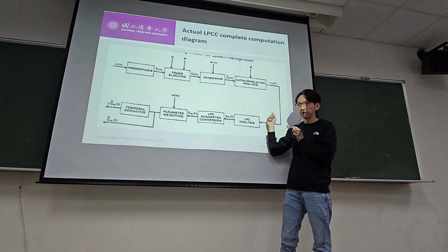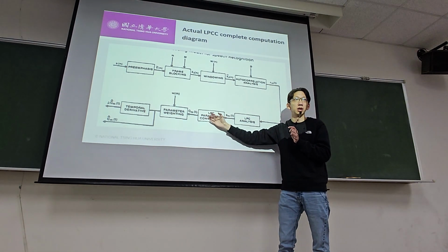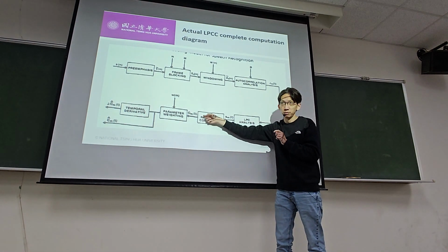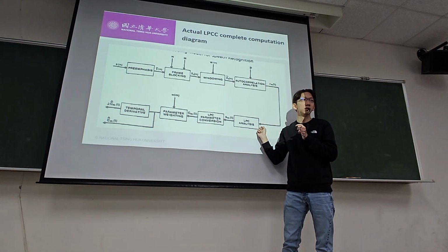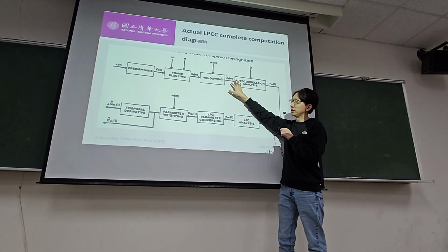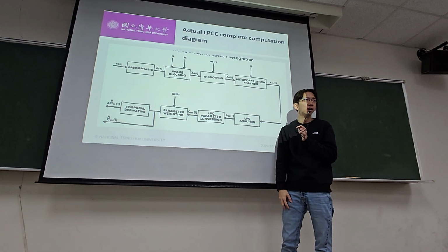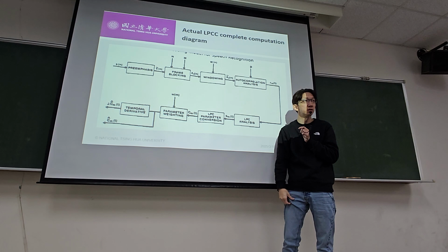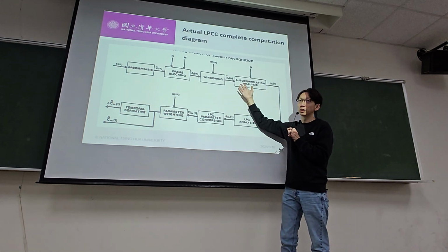If we describe the spectrum as the Mel scale, then that's the MFCC. If you describe the spectrum as LPC analysis output, then that's LPCC. If you don't do anything, just Fourier transform, that's a direct cepstrum analysis.